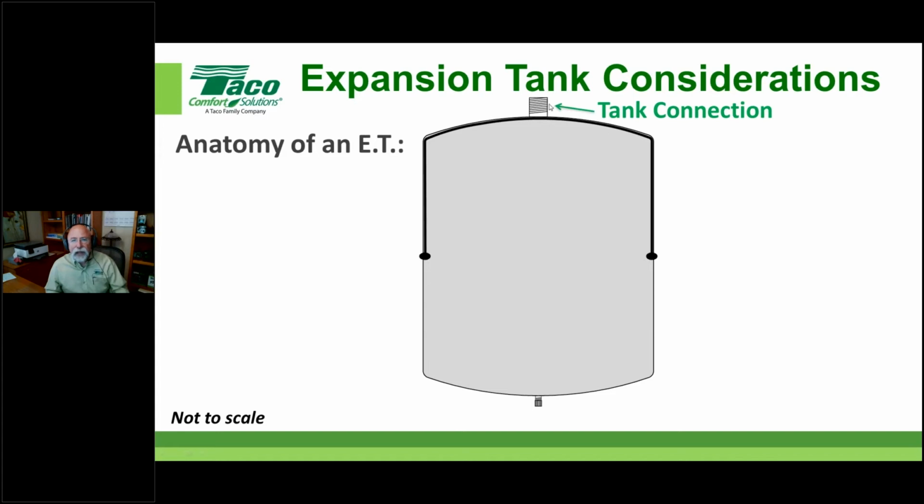The tank connection, generally speaking, on residential applications is half-inch male thread, male iron pipe, and that's usually the only interface we have with it. We've got right around this edge right here. We'll typically have a spot to put a wrench on and tighten it up.